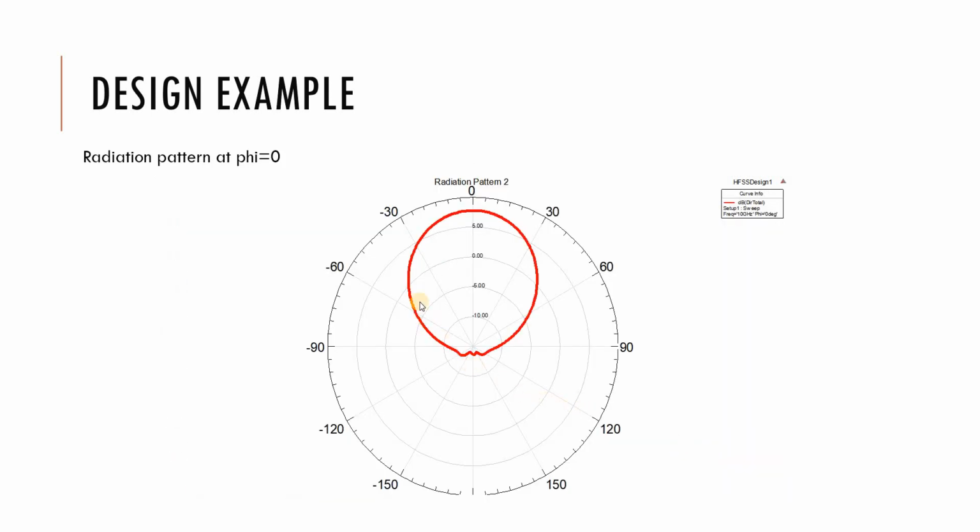You can see the radiation pattern. The directivity is going to 5 to 7 dB, as you can see here, and we move on to the HFSS and see the radiation pattern. It's in the E plane of the antenna. We're going to see the H plane. If you see the H plane, you can see the side lobe of the patch antenna.